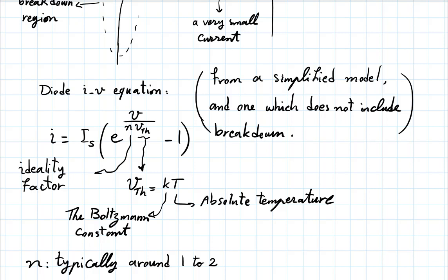Now, depending on your interests, this could be a very fun exercise or a painful exercise. Even if you find it fun, you might find it not very practical. Imagine you have a circuit with 10 diodes, each of which has a voltage and a current, and they're all connected with a bunch of other elements, resistors and capacitors and so on. You're writing your system of equations, KVL, KCL, or nodal and mesh analysis. Inevitably, the element relationships show up. For each diode, you have a highly nonlinear equation, and you have to now solve this system of coupled nonlinear equations. That's not very practical, especially if you're trying to design something.